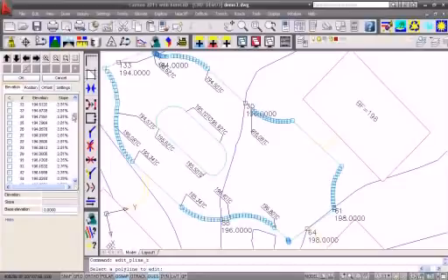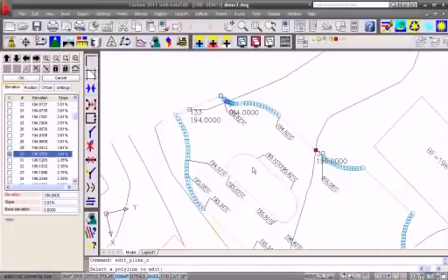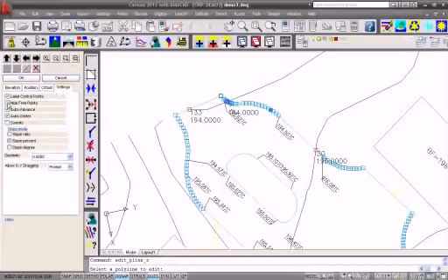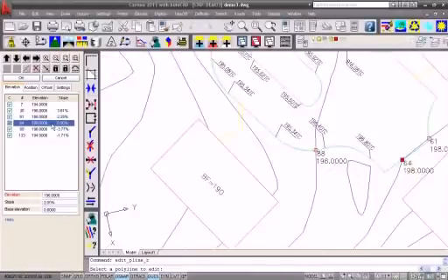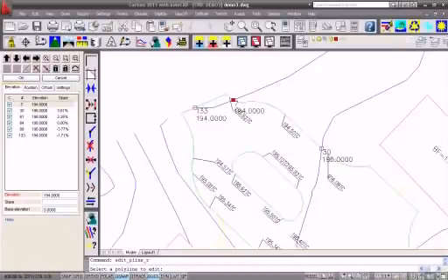I can see all the points on here. So anything that's checked is one that's been set by those contour lines. So 194, and I can go down. Here's 130. It shows me on the screen highlighted where that point is. And then all these points in between are interpolated. One setting we have here is hide free points. If I look at those elevations, now we just have a list of the control points, and I can cycle through. But we don't want to use just those points.